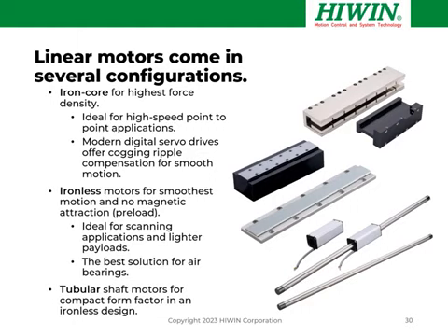Another type of ironless motor is the tubular shaft motor. That gives it a unique form factor that is sometimes suitable in designs, and they tend to be ironless. Iron core versions can also exist, but most often they're ironless. And you can move either the shaft or the moving coil. That's the case with all linear motor types: you can move either the magnets or the coil.